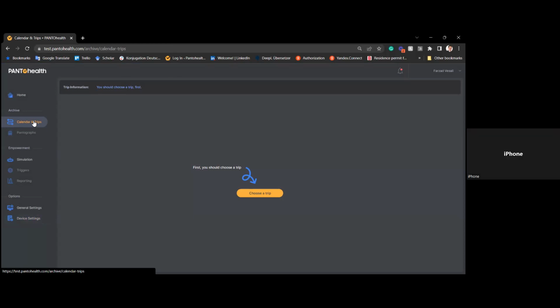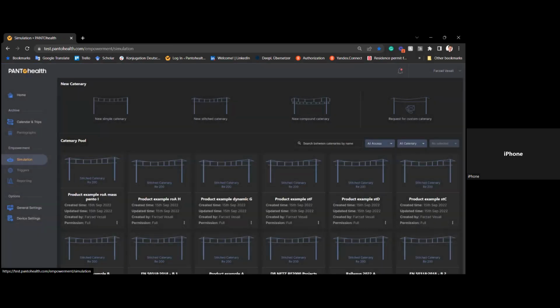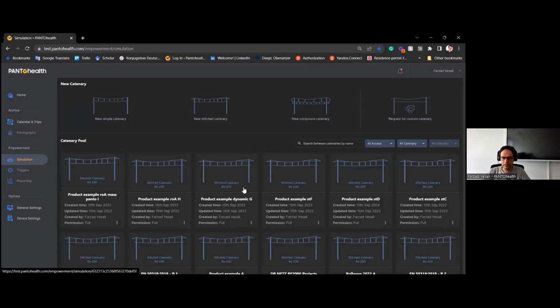Further, I suppose it could be used quite a lot in positioning section insulators, because there are point loads in the system, and they will require a special type of droppers and special spacing of droppers around that section insulator. So I suppose that would be one area where I can see a good benefit from this. Yeah, thank you for mentioning that. Definitely. The weight of the section insulator, and the droppers which are handling the section insulator, should also be designed, and this software can simulate this design as well.